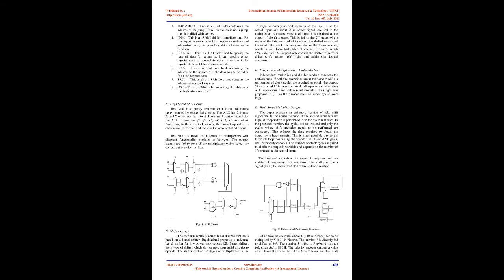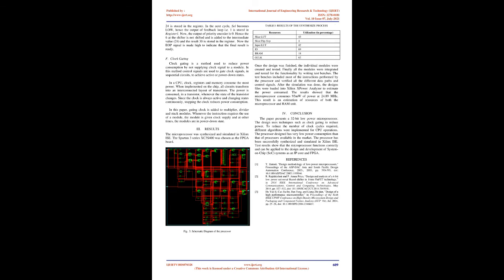E. High-speed multiplier design. The paper presents an enhanced version of the add/shift algorithm. In the normal version, if the second input bits are high, shift operation is performed, else the cycle is wasted. In the proposed version, the cycles are not wasted and only the cycles where shift operation needs to be performed are considered. This reduces the time required to obtain the output by a huge margin. This is made possible due to the feedback loop, containing the decoder, NOT and AND gates, and the priority encoder.